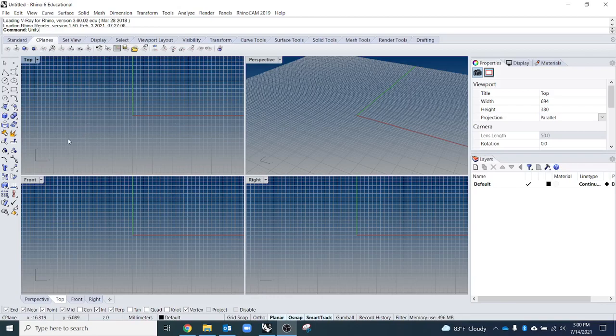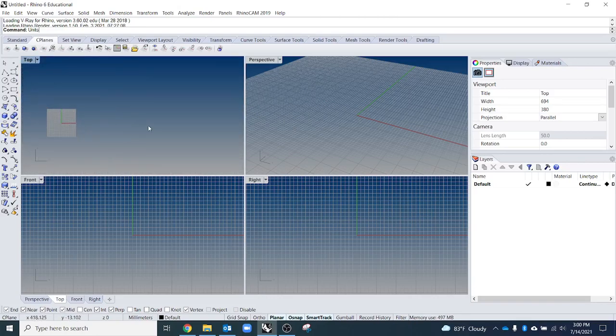So in this video, I'm just going to show you this is what Rhino looks like when you open it up, or it should look at least similar. So you'll see what are called different viewports, and in those viewports, you're basically looking in different directions. So I'm just scrolling in one viewport to move in and out. Basic navigation, right click to pan. See my little cursor turns into a hand, and I move back and forth, up and down. And you can also orbit.